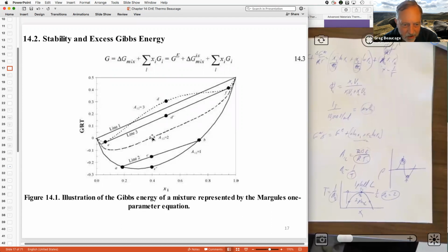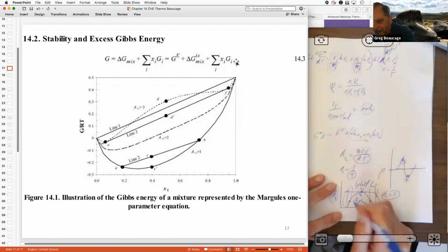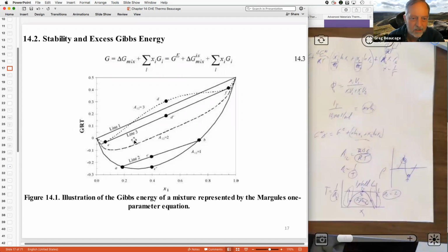If you're above the critical temperature, or below on the A scale, you're single phase. If you're above and you get this kind of double minima curve, then it's going to phase separate into those two points. If you're at the edges, it's still single phase. So here, this is all single phase at the edges, and then in the middle, it's two phase. So that's just showing how this free energy relates to the phase diagram, how they're tied together.